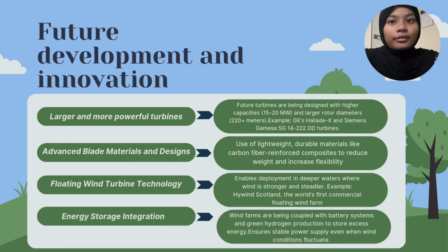On to the next one, future development and innovation. For the first innovation, use larger and more powerful turbines. Future turbines are being designed with higher capacities, 15 to 20 megawatts, and larger rotor diameters of 220-plus meters. Examples are GE's Haliade-X and Siemens Gamesa SG 14-222 DD turbines.